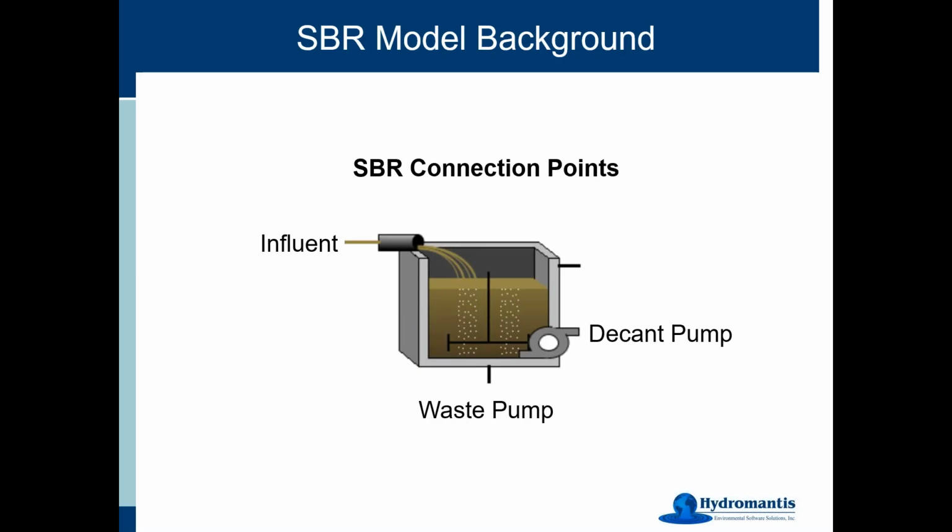And we won't be going into it in too much detail today, but just know that you normally would decant off the top layer as you're pumping it down, but you do actually have some control in order to be able to pump off of whatever layer you like, and also decant only down to a certain minimum volume, if you like. And then, of course, we have our overflow connection point. So now, theoretically, if you've got everything set up properly, it won't overflow, but typically that's where that would happen.